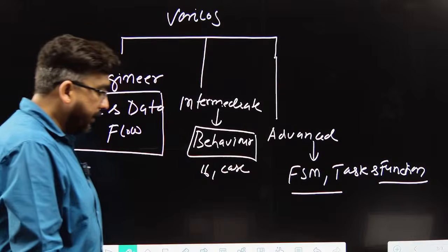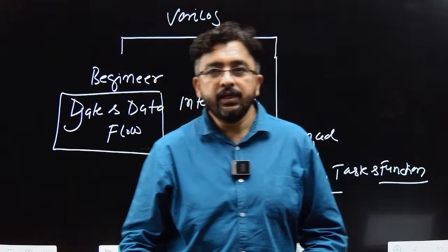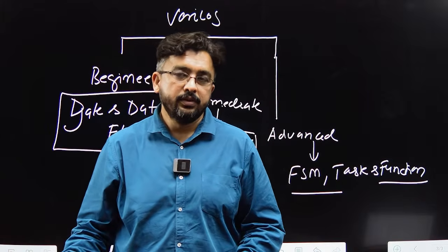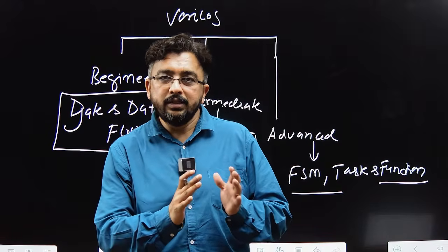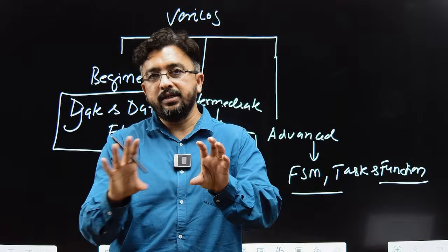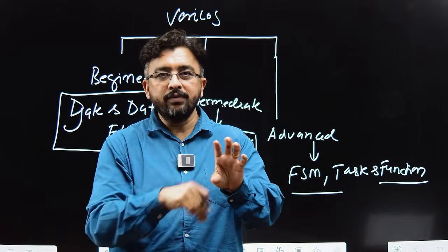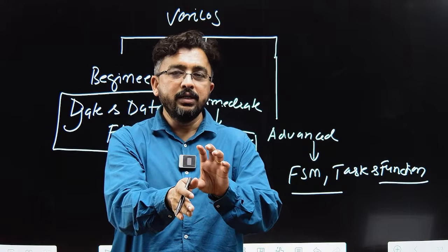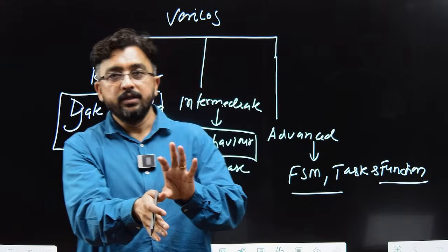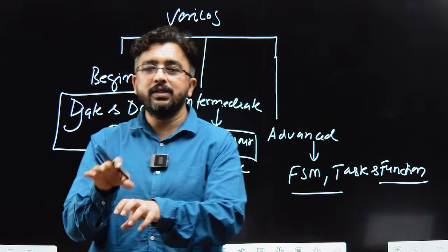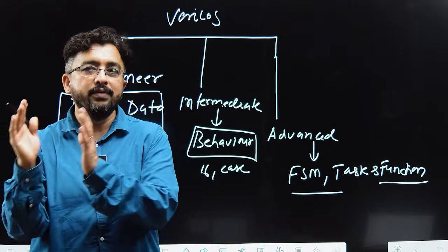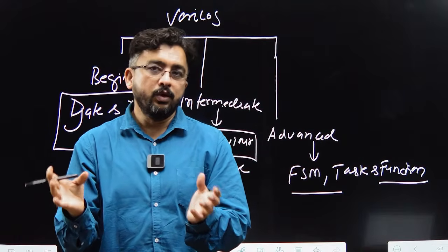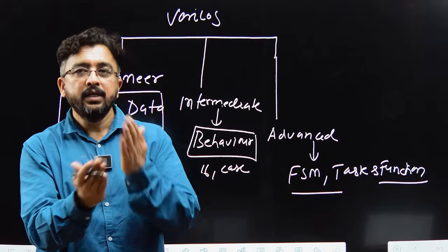So in my class, we are not working on those circuits or those syntaxes which are used for verification. There are two things: design and verification. Design means RTL design, Verilog and VHDL, 100% synthesizable circuit. Every output should be converted into a gate level netlist. Whatever you have designed, you have to verify with SystemVerilog and UVM, and that is called verification. So design and verification are two different domains.